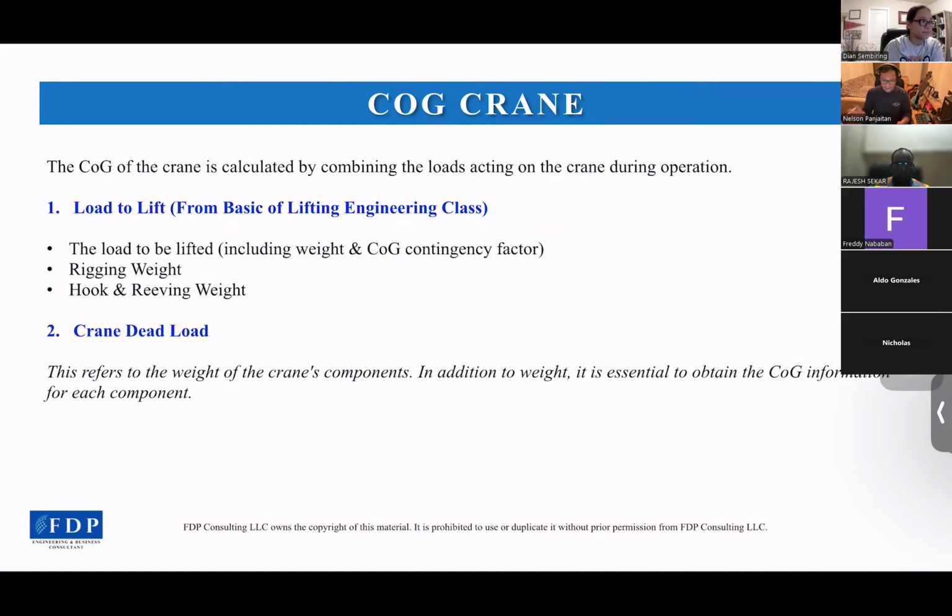But sometimes we also include the dynamic factor in the calculation, so it will give us more contingency for the ground bearing pressure. But in some conditions, for example, if we use a suspended superlift counterweight, the load will no longer be realistic and lead us to an unrealistic superlift requirement. And if we use an unrealistic superlift, maybe during operation it will be okay.